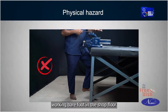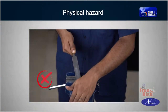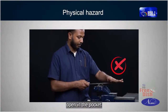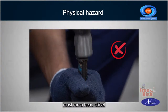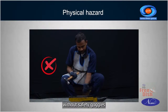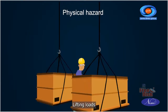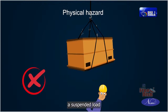There are some more physical hazards such as working barefoot in the shop floor, using a file without a handle, striking on a chisel head with a ball peen hammer without wedge, keeping a scriber with the sharp edge open in the pocket, chipping a metal surface with mushroom head chisel, chipping on a metal surface without safety goggles, lifting a heavy load with damaged slings, lifting loads while people are working nearby, standing below a suspended load.